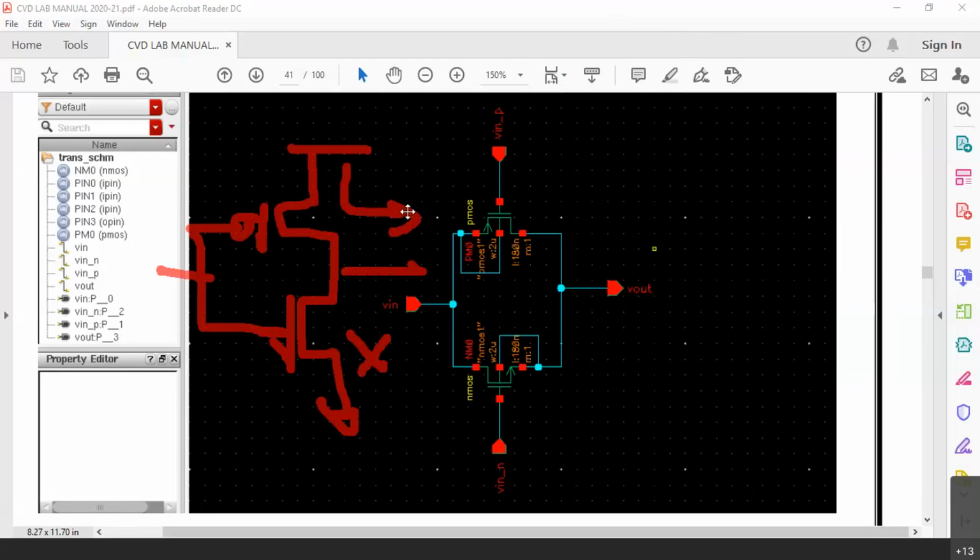But there is a dynamic power dissipation, which means when PMOS is on, it is going to charge the load capacitance at the output. So there is a dynamic power dissipation in a regular CMOS inverter. There is no static power dissipation. That is the advantage of CMOS when compared to BJT, because in BJT there is a static power dissipation. Let me write the BJT circuit.